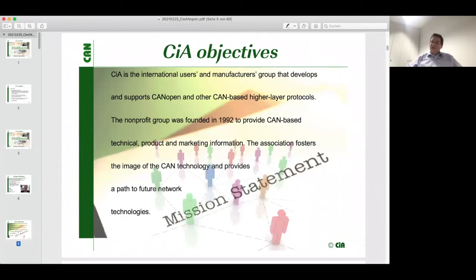So, by the way, the history of CAN has not been written yet. We are still writing on the history of CAN. So, we accompany the development of CAN-FD, CAN with flexible data rate. Let's say, the technology generation that is currently coming into the market, into the cars and other application fields. And on the other hand, we have now high frequently working group meetings that are discussing already the next generation, CAN-XL, that allows us to transfer a very large size of data in one single CAN frame. So the objective is to tunnel, for example, Ethernet frames with 2K of data inside. So you see, we are still developing in CAN. The development on CAN has not stopped yet.